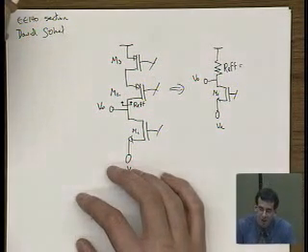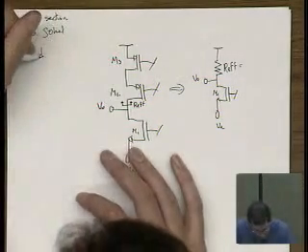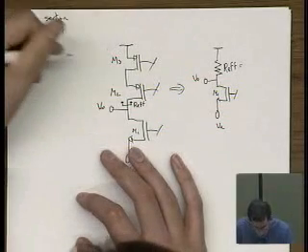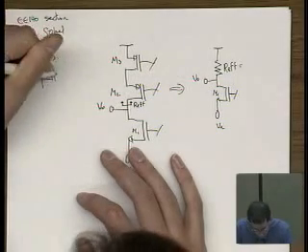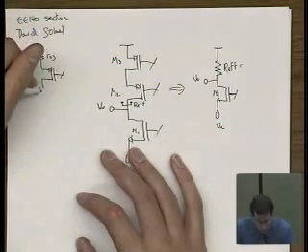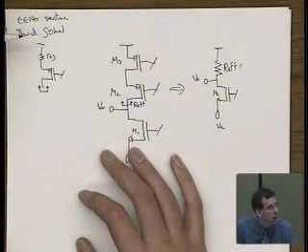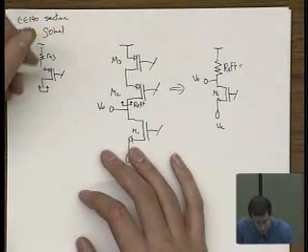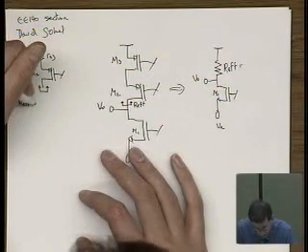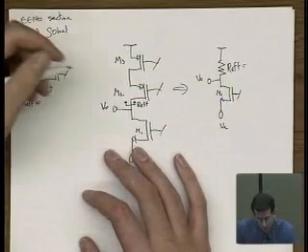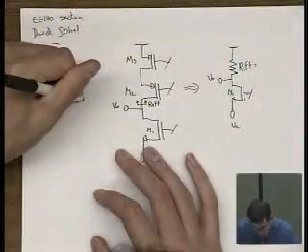I just know it's a source-degenerated resistance. Exactly. So what you can do there is you can say, oh, M3. That M3 just looks like an R out 3, and then we've got this, right? And we're saying what's the resistance looking up there? That's just a source-degenerated common source stage, and this is M2. So R effective is approximately, and I'm dropping out some of the smaller terms, gm2 ro2 ro3.